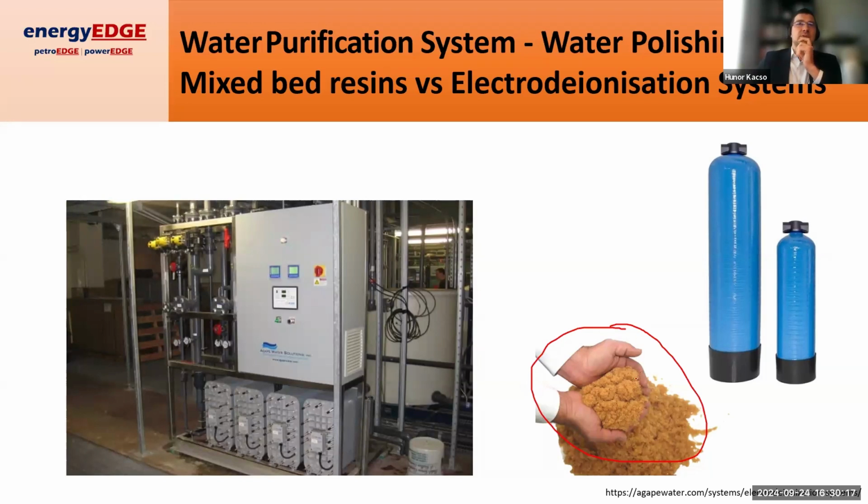So what we have to do is every so often, every, let's say, 6 months or 8 months, 4 months, you would have to go on site and replace the DI resin inside of these containers. And the trouble with that is, of course, it increases maintenance, and also it's a cost.